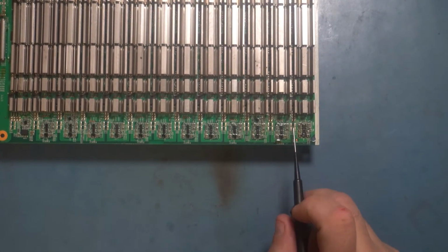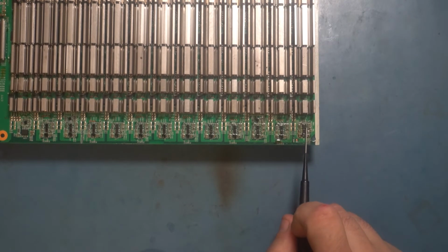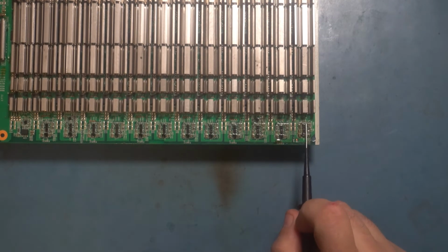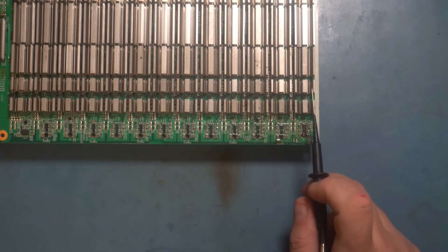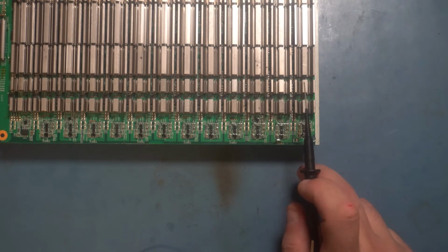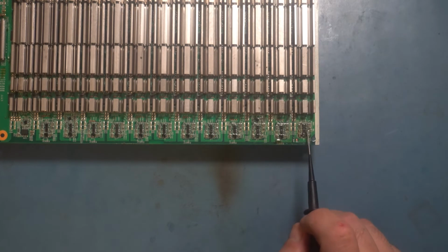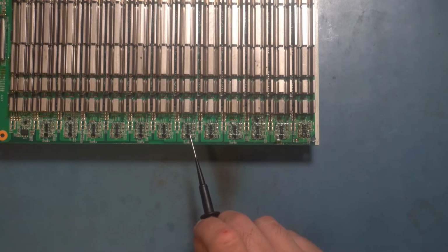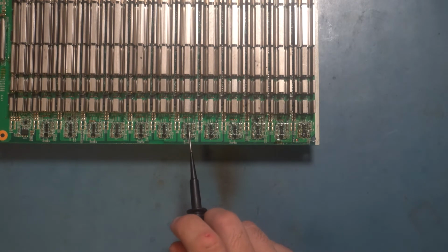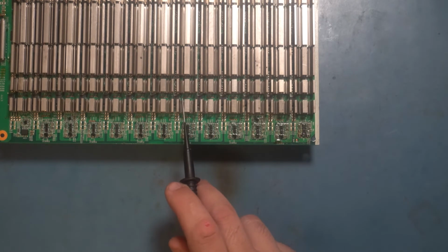But in order to generate 1.8 volts for each domain, that 1.8 volts needs to be relative to that domain's ground, if that makes sense, right? If I'm in the first domain, there's going to be 1.8 volt relative to the first domain ground, which is the main board ground. If I'm up at the 6th domain, then those chips need to see 1.8 volt relative to their own ground.